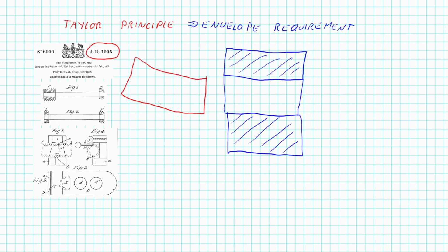That shaft may have a bit of a banana shape to it. And say that we have made the tolerances so they should fit together. So maybe for the hole here, we have given it a dimension, a diameter of 10, and it can be plus 0.1, and it can be down to 0.